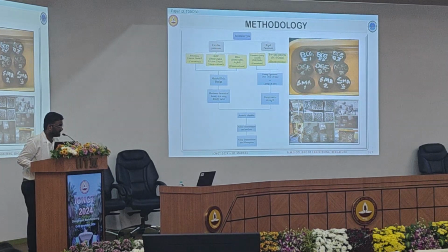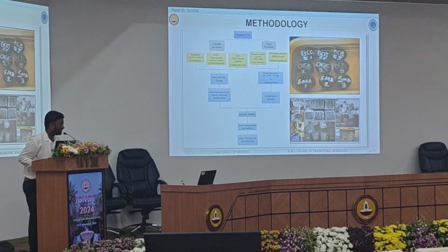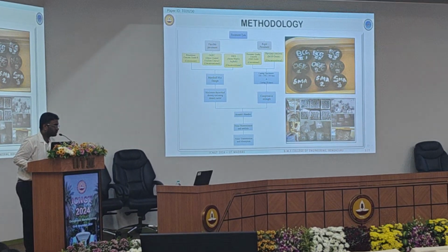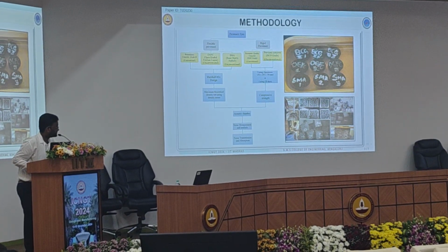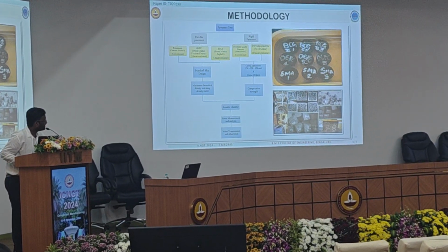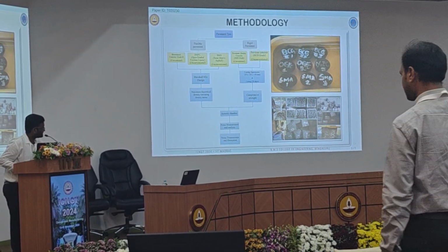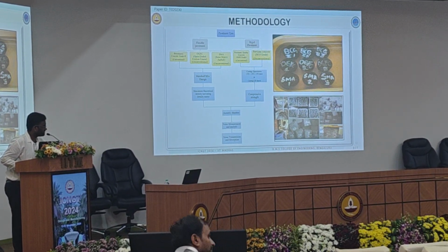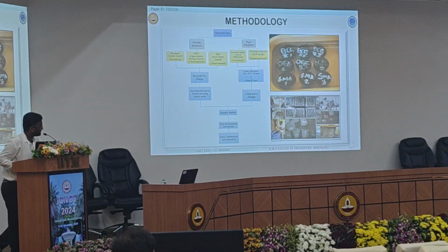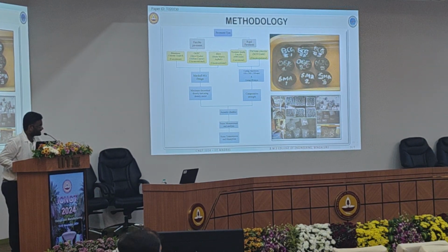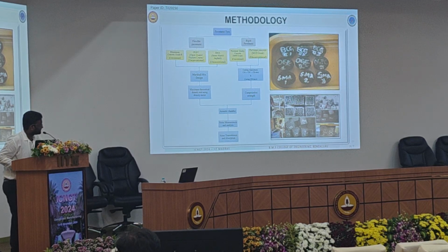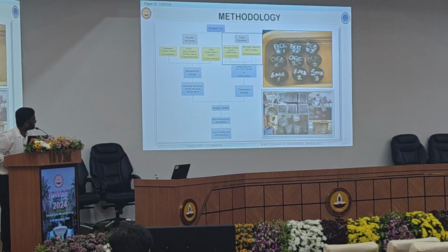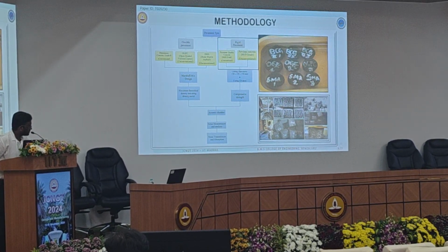In order to study how structurally strong and durable the material is, the Marshall mix design test was carried out, and to analyze the air voids in the specimen, maximum theoretical density was used. In case of rigid pavement, considering the conventional concrete, that is PQC, pavement quality concrete, designed for M40 grade, it was compared with the unconventional pervious concrete, which was designed for M10 grade. The specimens were cast for the Marshall specimen. The specimens were cylindrical. In case of the rigid pavement, the specimens were cubical.